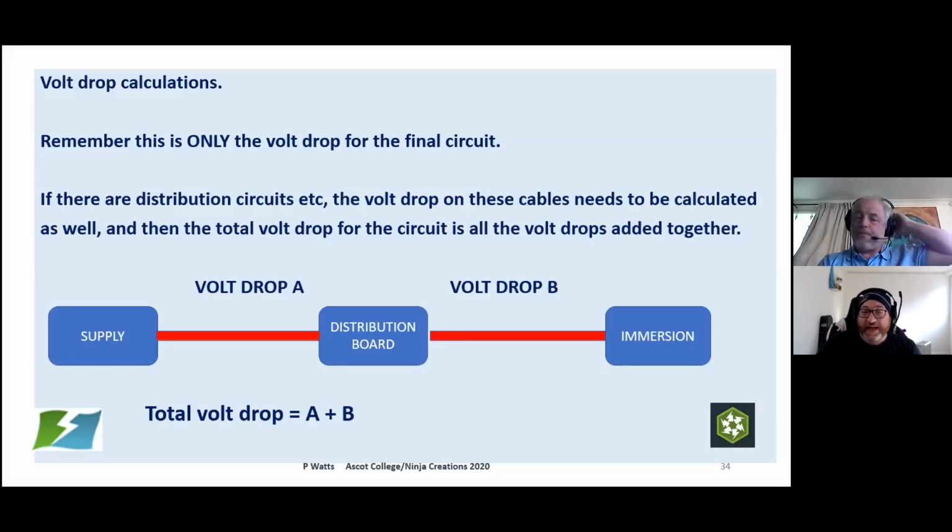We'll have books like this, though, where the maximum lengths etc. are calculated, and it's just transposition. Assuming we had the R1 + R2 and it was actually correct, with no parallel paths or anything compromising the value, and the value was an accurate representation of R1 plus R2, you could then technically transpose the R1 + R2 calculation formula. So R1 plus R2 is milliohms per meter times length over 1,000, so that would become length is equal to your R1 + R2 over the milliohms per meter, and then multiply that by 1,000, and that would give you a calculation of the length from the R1 + R2. But your R1 + R2 may not be purely representative of the cable's resistance itself.